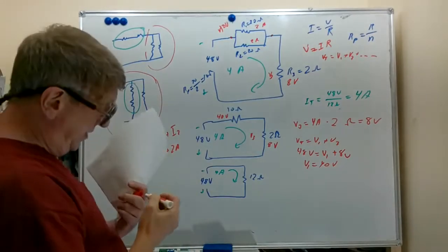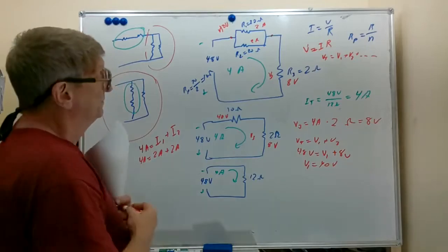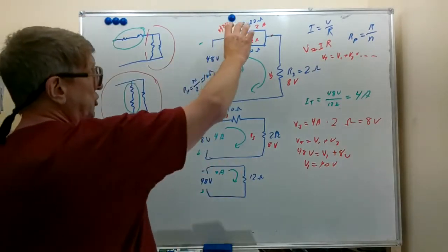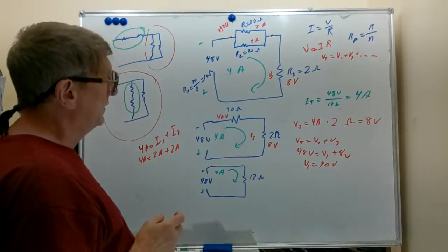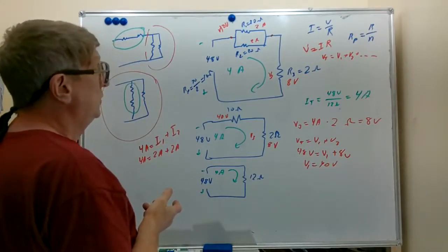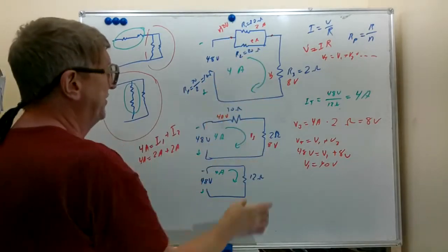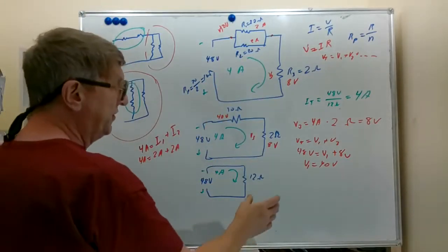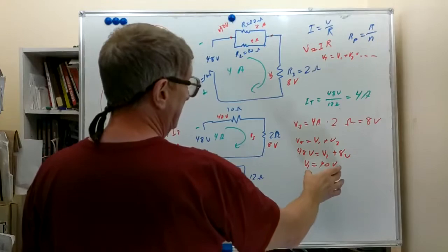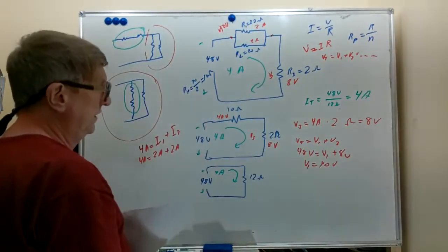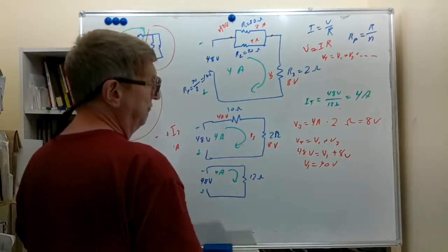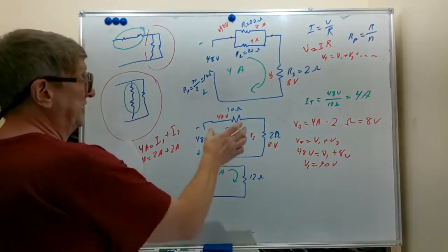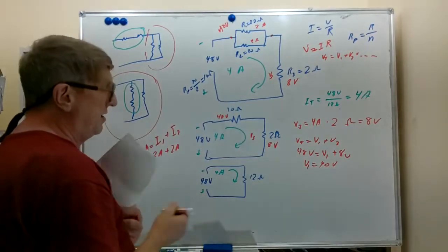Now the other way we can solve those currents through these 2 parallel branches is we could have calculated the voltage here, which I believe we've already done. Yeah, we have 40 volts here. We used our voltage total formula for a series circuit to get the 40 volts here, which also goes up there.